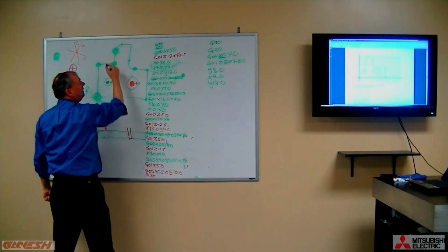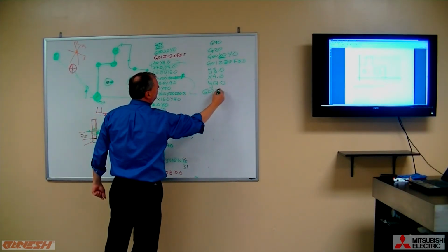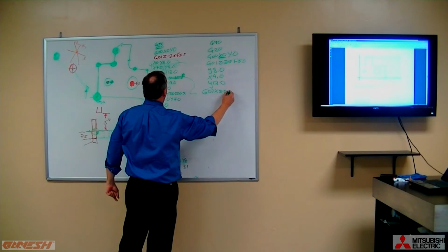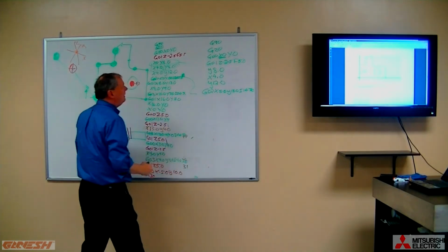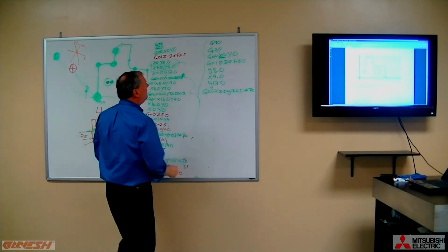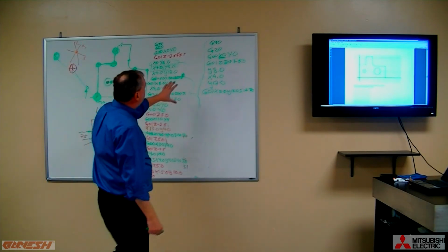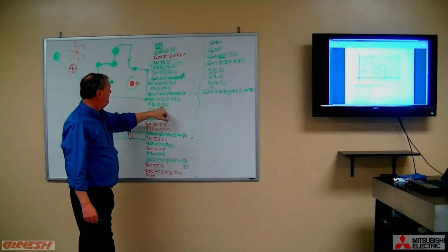Now we're sitting right here, and then we insert the G02 the same way. We say G02, that has to have both of them because they're going to be different, right? So X5.0, Y13.0, I plus 1.0, J0. And so on. So we're eliminating more typing, and now we're starting to resemble what you'll commonly find out on the floor, a streamlined program that still moves to the same axes but does not repeat redundant information,